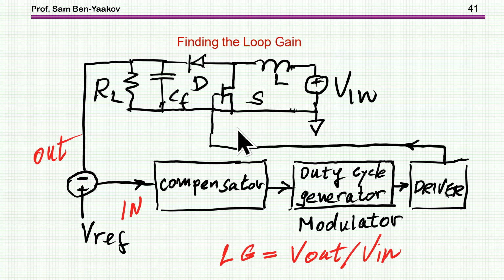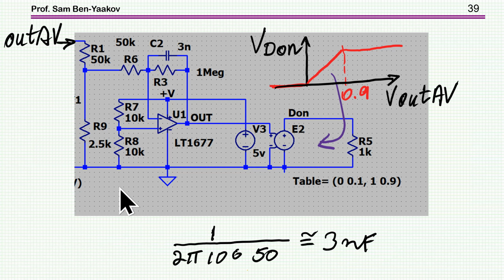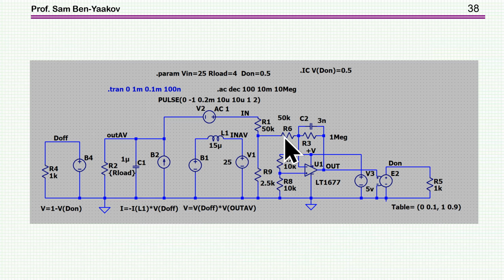This is fine. Now, I'd like to look at the loop gain, okay? Loop gain can be looked at if you can get the ratio between the output here and the input here around the reference. In real systems, it's very difficult to identify these two signals, because if you look here, you have a whole combination of the input and the reference, and it's not that clear what is in and what is out.